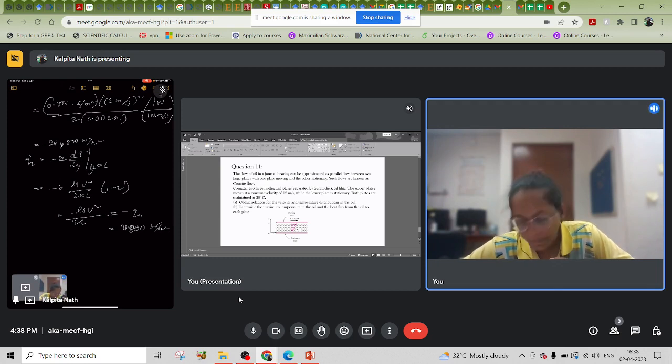A temperature rise of 99 degrees Celsius confirms our suspicion that the viscous dissipation is very significant. Also, the heat flux is equivalent to the rate of mechanical energy dissipation. Therefore, the mechanical energy is being converted to thermal energy at a rate of 57.2 kilowatt per meter square of plate area to overcome friction in the oil.